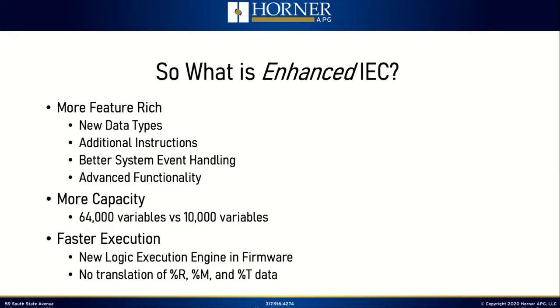Another thing to keep in mind is when you move to enhanced IEC, there is no longer any translation whatsoever when it comes to internal memory types. Of course, we still have external memory types, things like analog inputs and outputs, digital inputs and outputs, because let's face it, when you are configuring or programming your logic, you need to be able to create variables and reference specific I/O pins on the built-in I/O, for instance. So you're still going to have to map over to real-world I/O points. And we also have system memory, which is still relevant, system bits, system registers, those sorts of things.